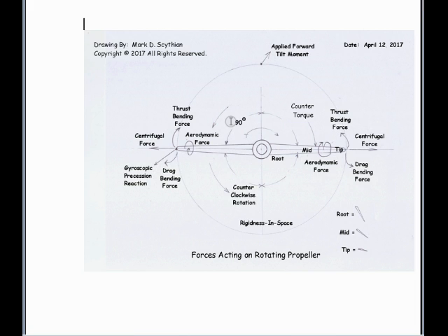And these are somewhat reinforced and stabilized through centrifugal force, although the aerodynamic force also is intensified due to the centrifugal force wanting to pull it out, causing an inclination of negative pitch to incur. So that's why the structural materials have to hold up to all of these different forces, especially the aerodynamic force and the centrifugal force wanting to pull the blade apart and also decrease the pitch of the AOA, offsetting the properties and the specifications of the given propeller blade. So it cannot deform due to centrifugal force and aerodynamic force.